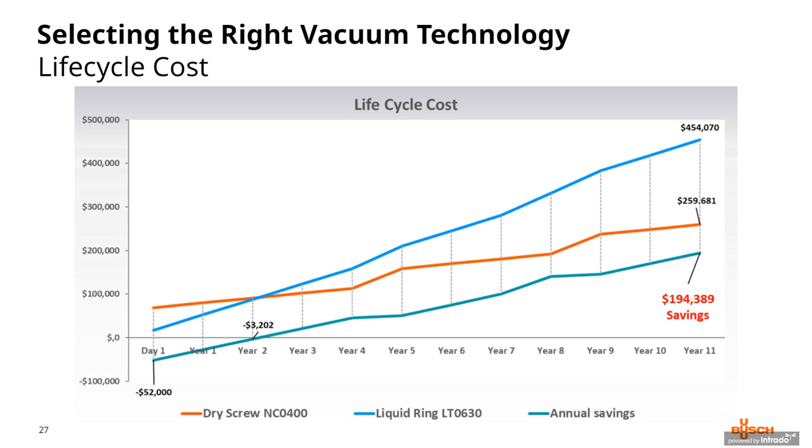Now here you can see the total savings, and that becomes more significant after the second year. If you remember, we selected a once-through system due to the methanol. Now, a full recovery would actually utilize more utility water in most cases. This is due to the additional requirement that we have a heat exchanger that also needs cooling water, even though the majority of the seal water is actually recycled.